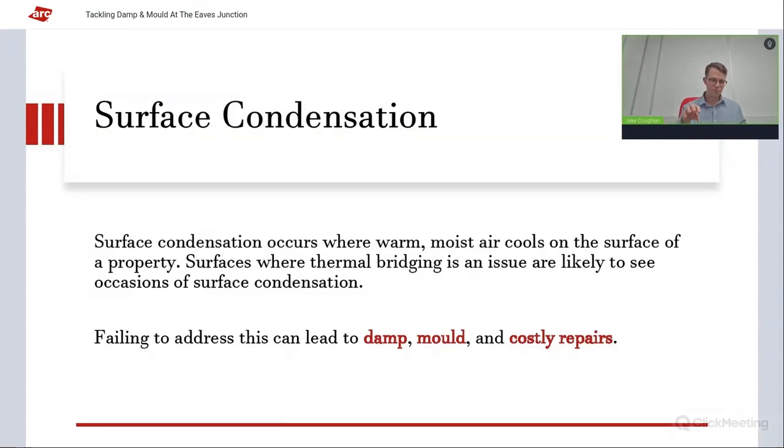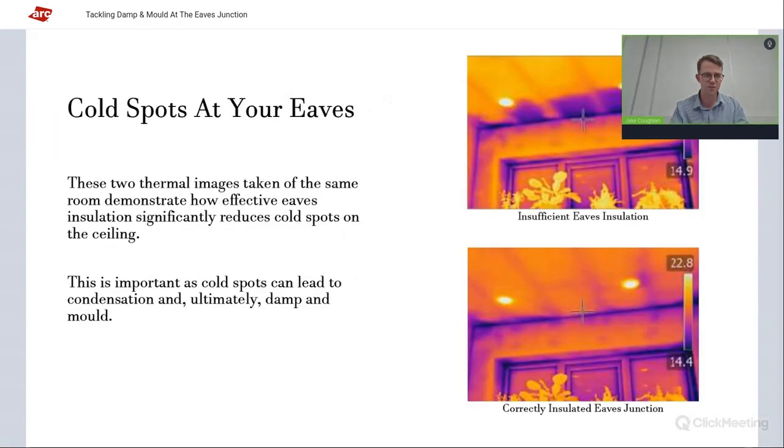Additionally to that, we're in an ecosystem ourselves. We've got lots of bacteria, lots of mold just in us naturally, as is normal. And that is also coming out and condensing and being part of what ends up at those cold spots. So really, I'm trying to make it a little bit more real, is why we don't want cold spots on those internal surfaces. And this is a prime example.